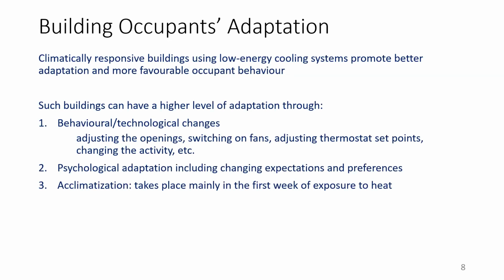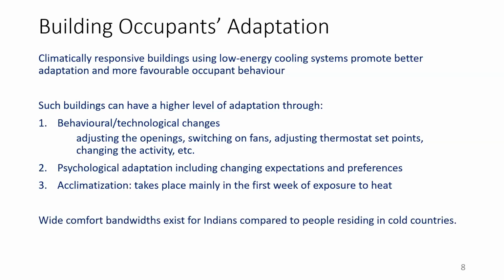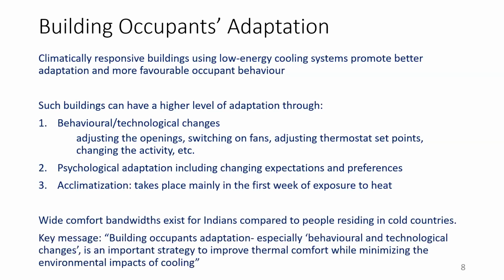And finally, acclimatization, which mainly takes place in the first week of exposure to heat, is also equally important. And this has come out of many field studies that Indians have wider comfort bandwidths compared to people residing in cold countries. So the key message here is that building occupants' adaptation, especially behavioral and technological changes, is an important strategy to improve thermal comfort while minimizing the environmental impacts of cooling.